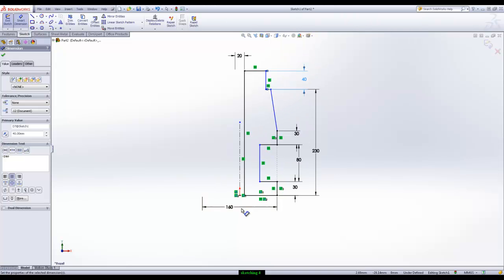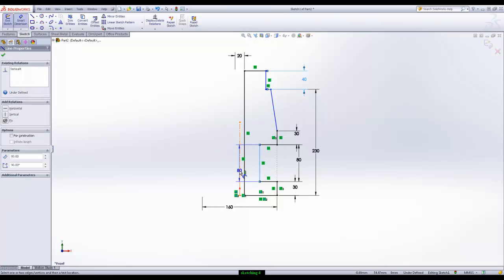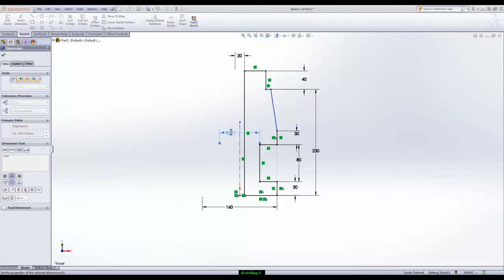But you can use the diameter for all of this. In other words, the one in the middle has a diameter of 100, so it's the inside edge, the center line. If you stay to the right, that's a radius. If you just move your mouse to the left, that's a diameter. On one side of the center line, radius. On the other side of the center line, a diameter. So that one there is supposed to be 100.